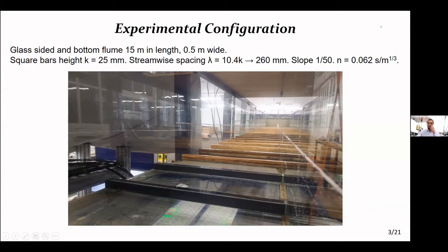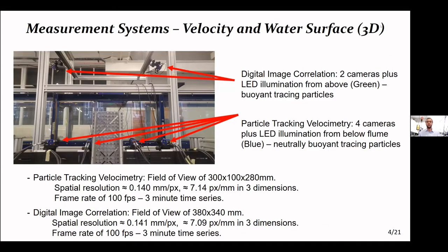Okay. The Manning coefficient was quite high for this type of bed. The surface behavior and hydrodynamics were investigated using two systems. For the hydrodynamics, PTV, so particle tracking velocimetry, was used, composed of 4 side view cameras.